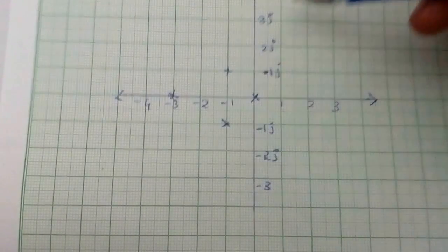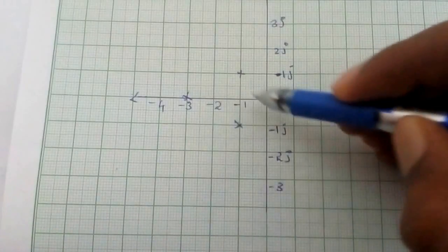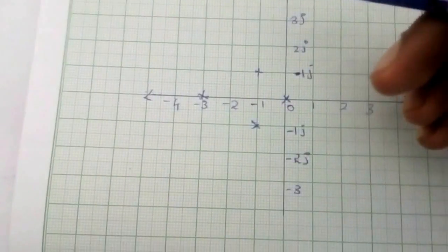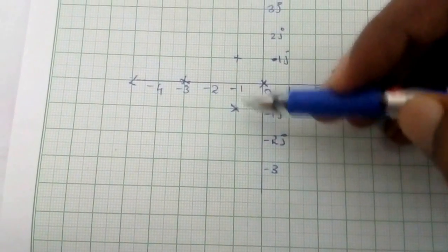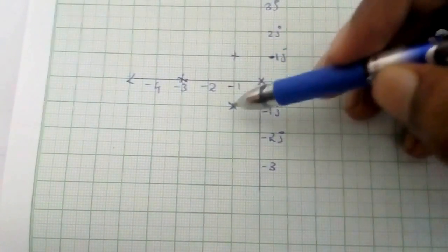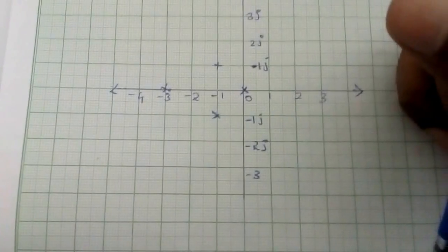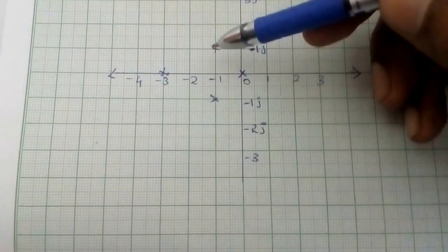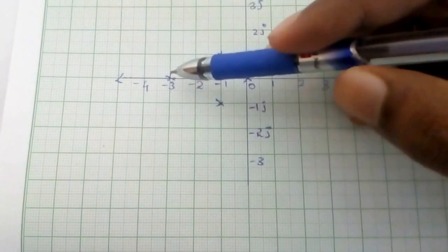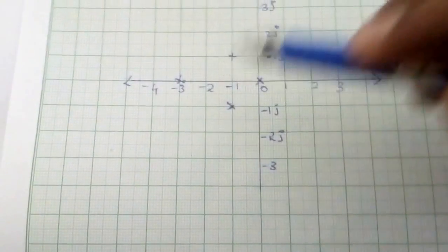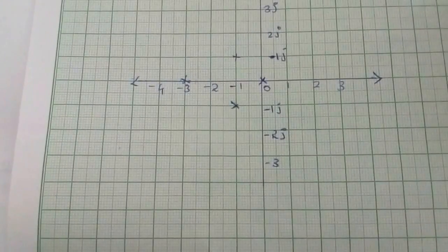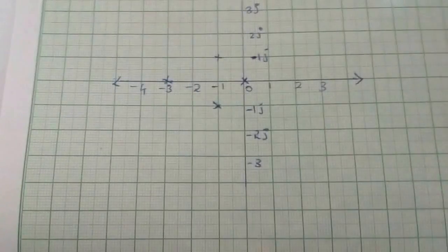The criterion for finding that region is this: when we take a point and look to the right side of it, if we have an odd number of poles and zeros, that section is in the root locus region.